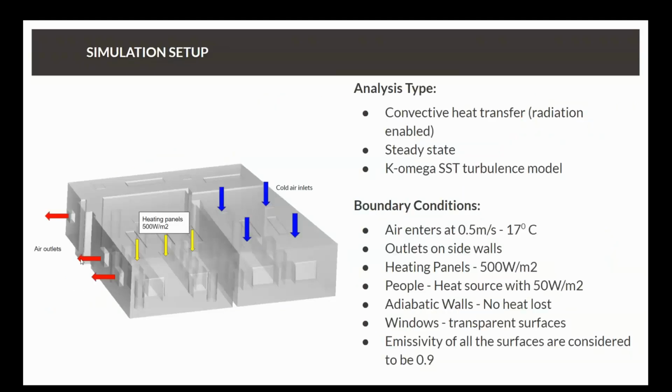Okay, and this is our setup. We're going to be using the convective heat transfer type of simulation in SimScale, which is basically only capturing the fluid volume, running it steady state, although we could, if we wanted to, run transiently, so things would then change over time. This is essentially asking, if we had this situation infinitely, what would the ultimate temperatures be?